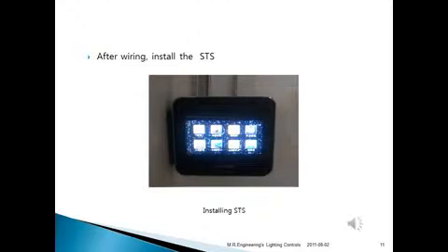After wiring and installation is completed, install the wiring into the inner panel of STS. Before installing the switch, the data from the factory needs to be downloaded into the switch. The last step is to place the cover on the STS.